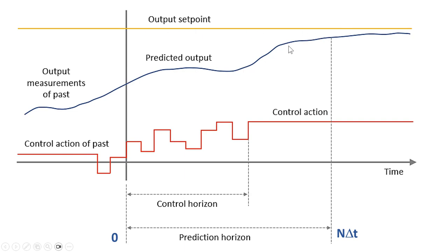So, the output of this process as shown in this graph is the consequence of finding the optimal values of the control inputs. And it was found by solving this optimization problem. And this optimization problem was formulated by looking ahead of the current time, and by utilizing the dynamics of the process that happens n time steps ahead. So, we predict its future behavior and try to control the process, or track the set point.